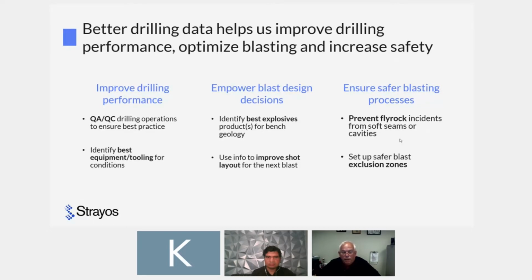Blasters, best explosives. Is it really hard rock? Are we getting into a hard rock seam that's brittle and easy to break, or is it soft and punky and more like a sponge? It also helps to improve blast layout. And you can see changes over time in benches as well as in performance. And this is all through measure while drilling.